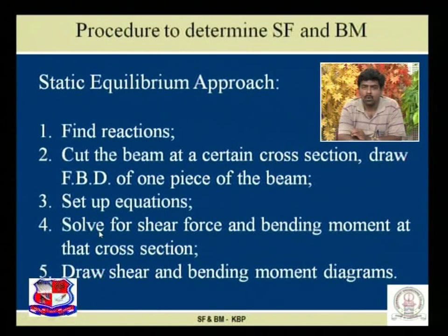Then we solve for shear force and bending moment at that cross section. After finding the shear force and bending moment at various sections, we can easily draw the shear force and bending moment diagrams.